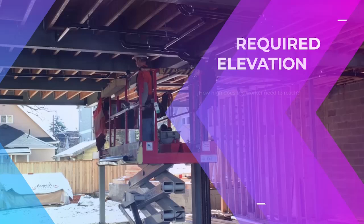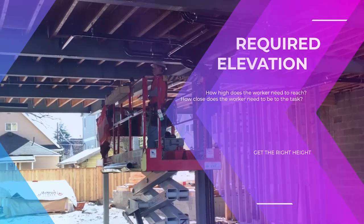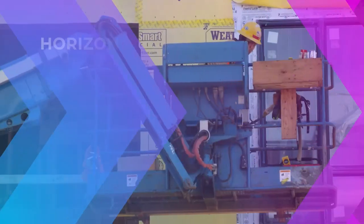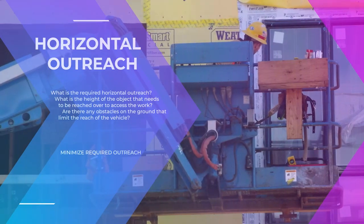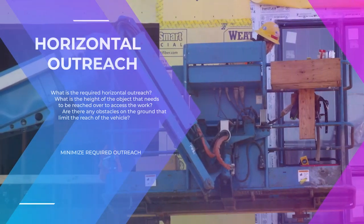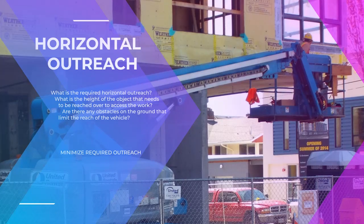The selection process should consider required elevation. How high does the worker need to reach? How close does the operator need to be to the work? Horizontal outreach. What is the required horizontal outreach? What is the height of the object that needs to be reached over to access the work? Are there any obstacles on the ground that limit the position of the vehicle?